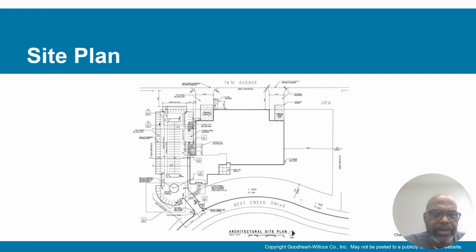A site plan is a plan that, if you were in a helicopter looking down on top of the building, you can see everything: the streets, the parking lot, the elevation. When I say elevation, they call it the grade. In other words, how high the ground is at different levels. If there's a hill or a valley, or you can tell that the ground is not even, it will be drawn on a print and they will show the different elevations.